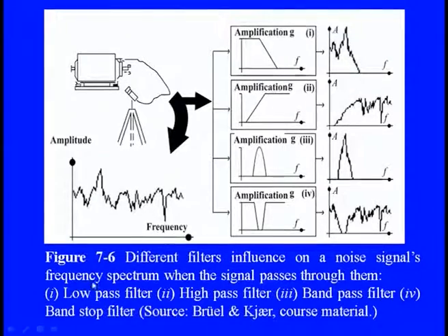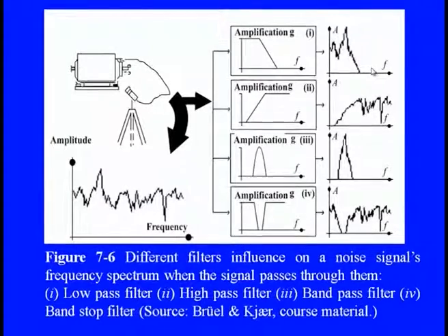and the entire remaining part is being restricted. If I look at the actual situation when this signal is passed through this low pass filter, then this is my frequency spectra with the low pass filter, and it clearly shows how the variations are at the low frequencies, in the exciting frequency with the amplitude.